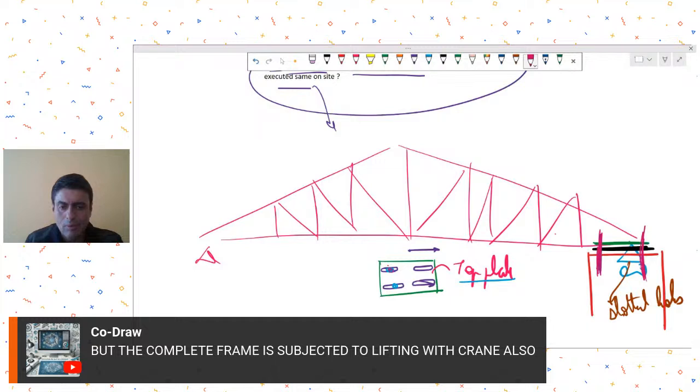So what happens? The bolts over here are fixed in concrete, and they are integrally connected to the black plate also. Connected means there is no translational freedom available in the black plate. Only this green plate is free to translate, I would say, because of the slotted holes. So one way is to have this kind of arrangement provided, and this can be approximated as a roller assembly. On the pin side, you will have no slots in the bottom plate or top plate.